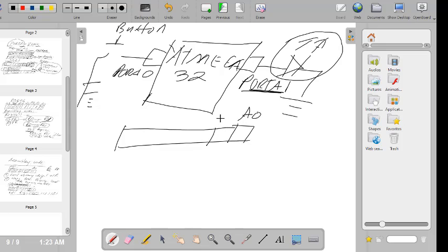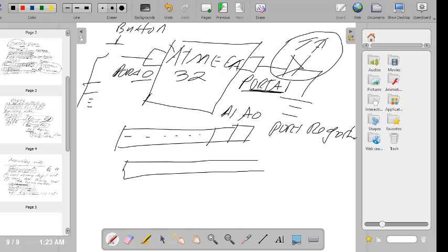So if now I'm dealing with just port A0 and this is port A1, then I'm beginning to think first of all, so suppose this is now to do with my port register. I don't care about others. I'm more concerned with port A0 and port A1. And now I also need to look at what is the data direction register of these ports.